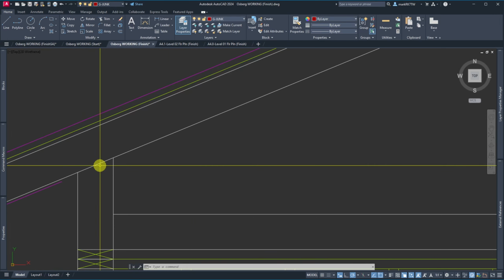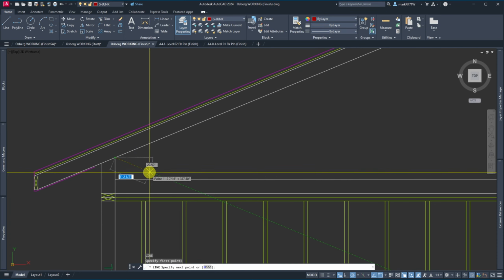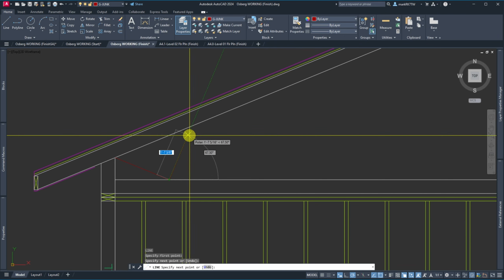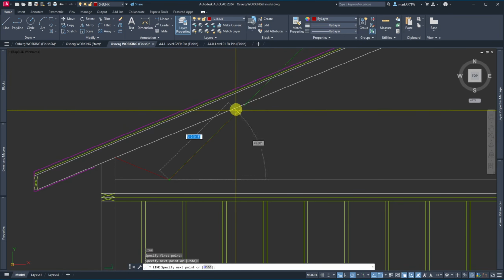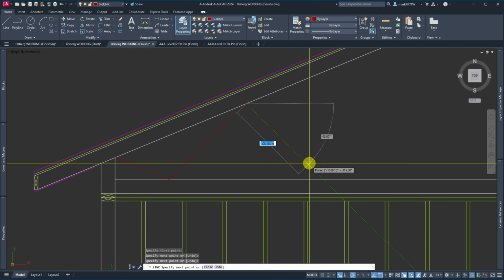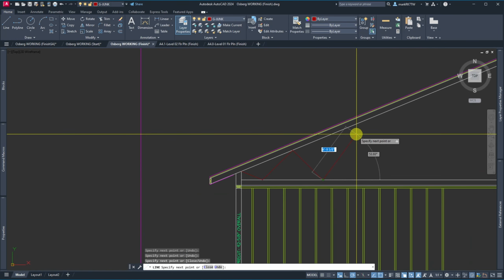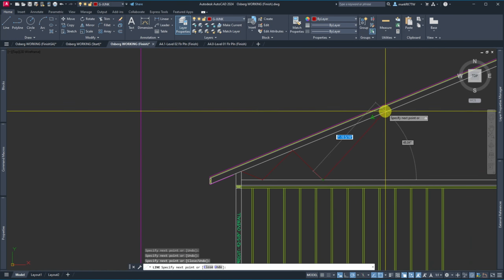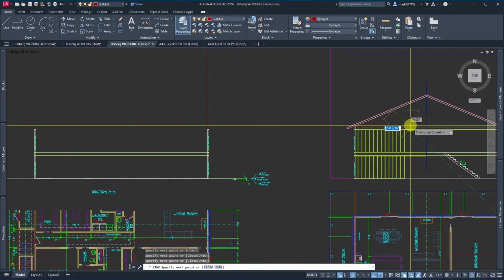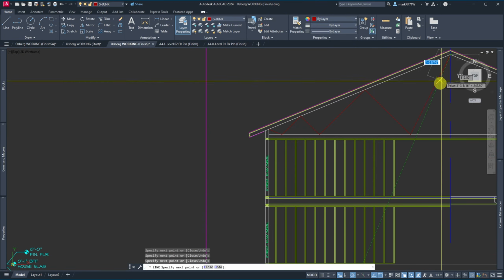And so one thing we can do to start this off is let's just start drawing in a truss. So I'm going to come at 22.5. It's one of my settings I keep, then 45, 67, 45. This just keeps me from having to do too much work by keeping some decently large increments. This is only a representation of a truss. And then 45 down again till I hit here, and then I'm just going to come up to that point.